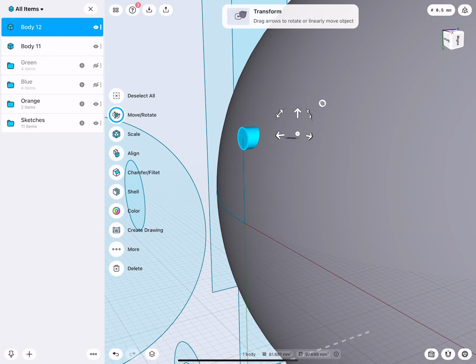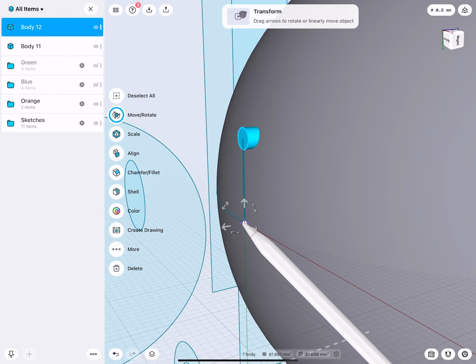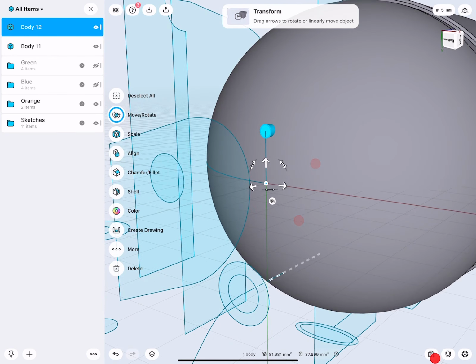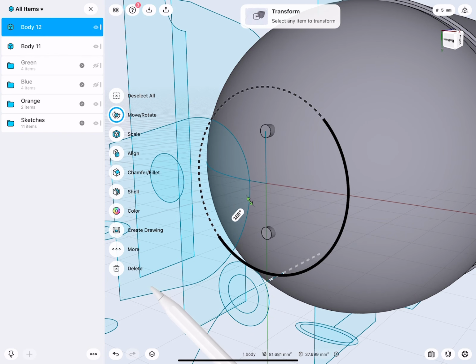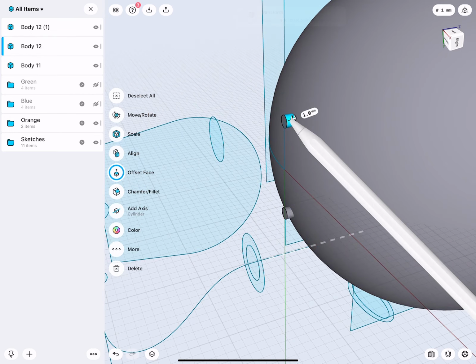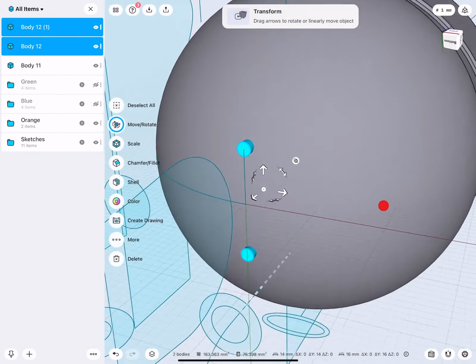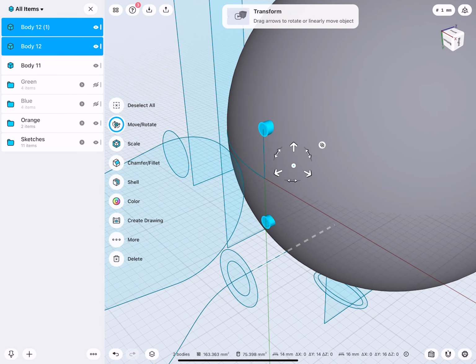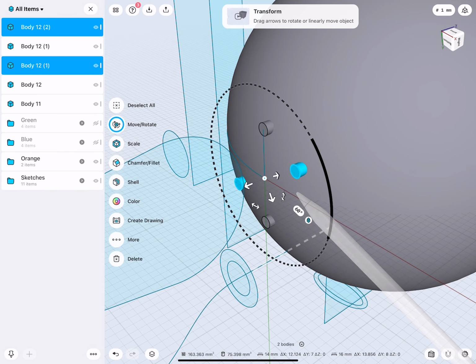When I selected a body by double clicking, you see I just created a new body. I didn't do a Boolean cut. Then I can move the gizmo to here, turn on this, to copy, and then make a rotation 180. Double tap both. This actually then should select directly the geometrical center. I'm just extra precise by moving this back onto the sketch. So I'm using actually the sketch here to snap to. Type in 60. Very good.